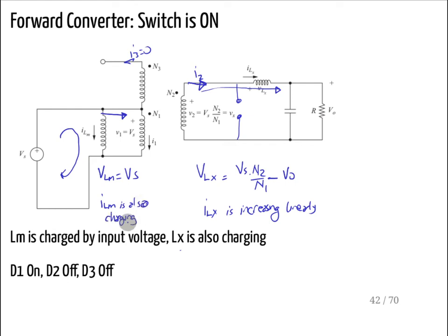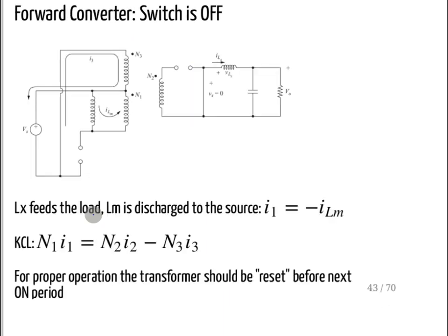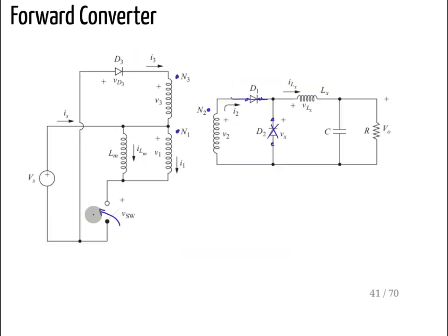That is still the case if you don't install the third winding, and if you don't provide any path for that current to go, if you turn off that path, it will create a large induced voltage, and you can destroy your switch, right? That is why we installed the freewheeling diodes in the buck converter and so on in the first semester.